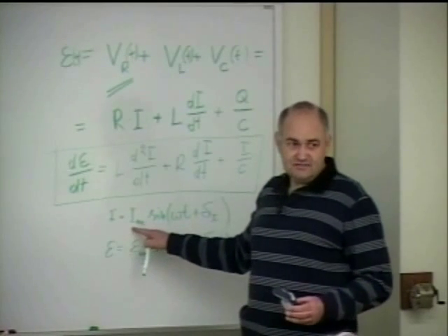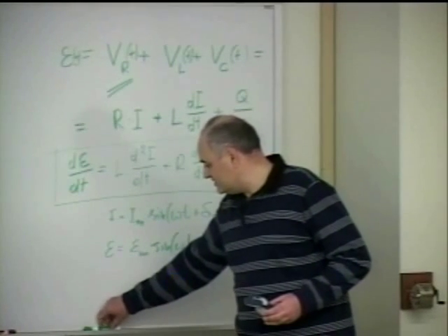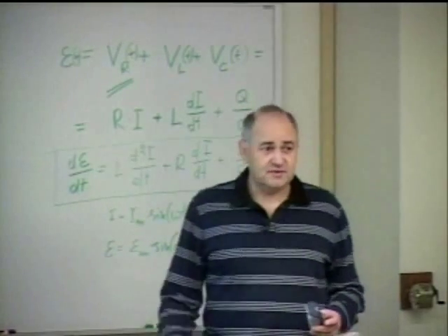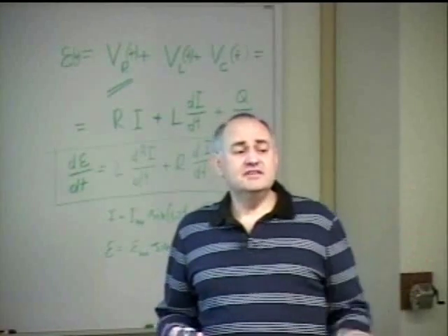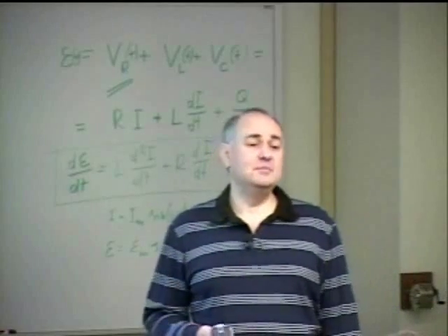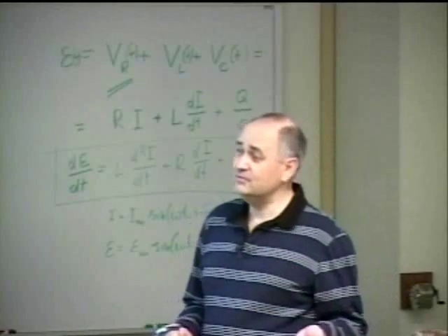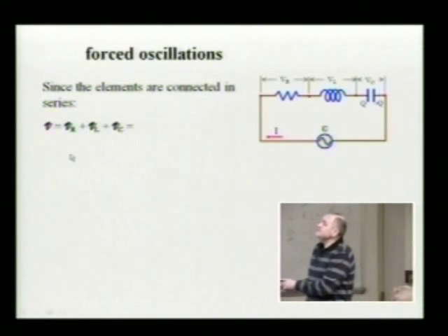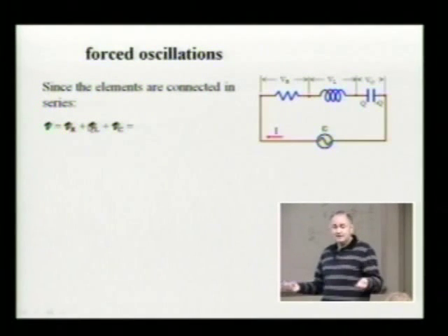All right. So in the result, the complex potential difference across an element is equal to the complex impedance of this element multiplied by the complex current, for all three elements. I'm drawing the phasor now. So let's say that here I have the phasor representing this current. This will be a good interpretation, a good comprehension of what we have over there. All right, so let's now draw phasors corresponding to each of the three voltages.